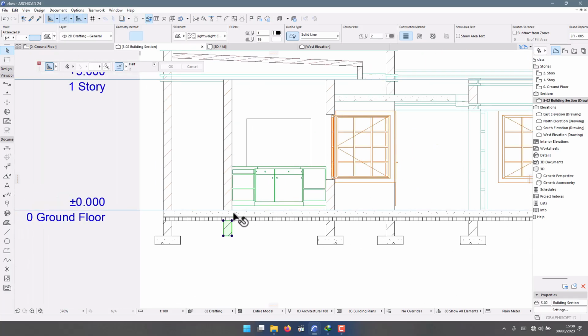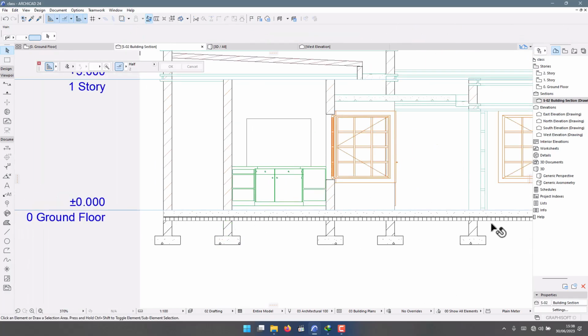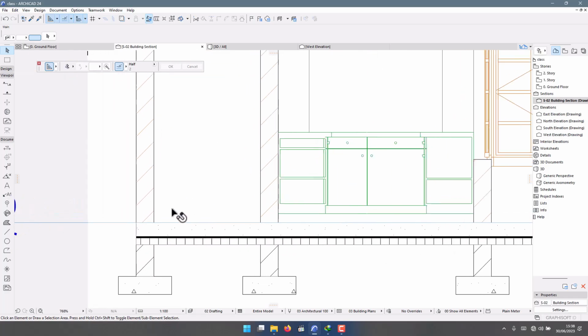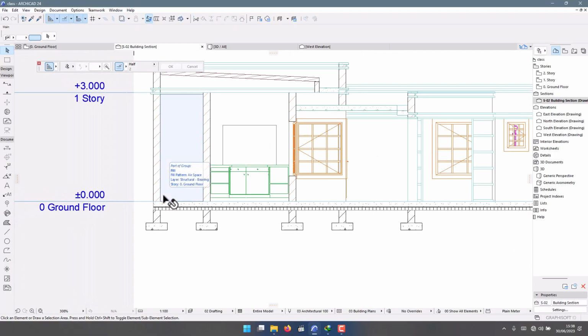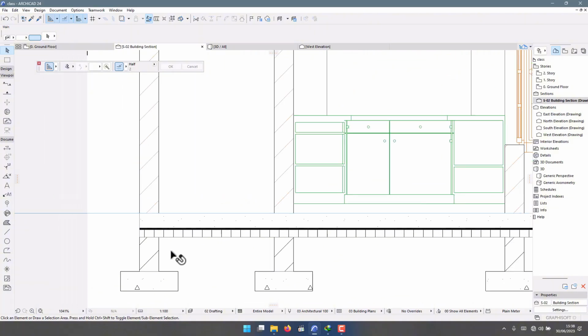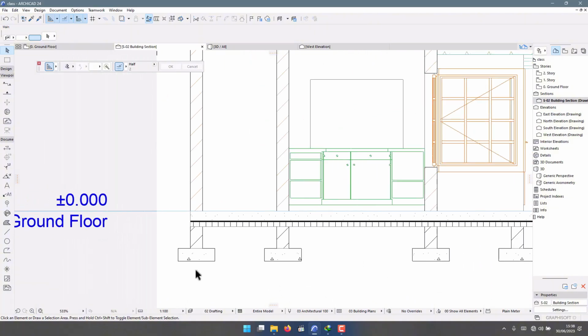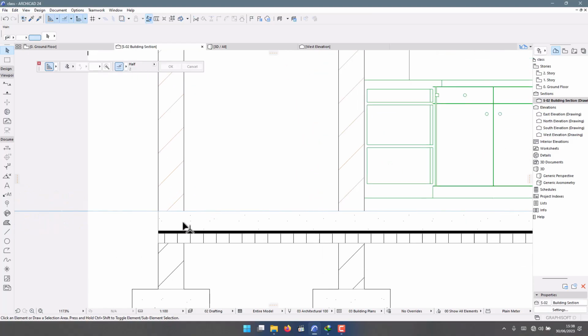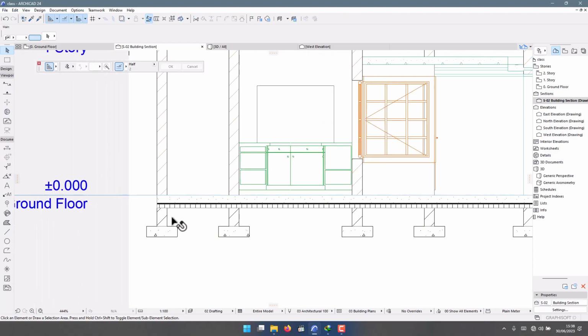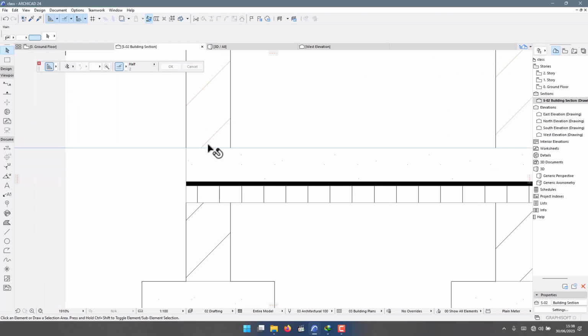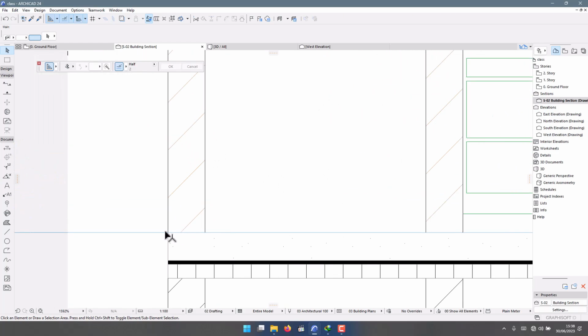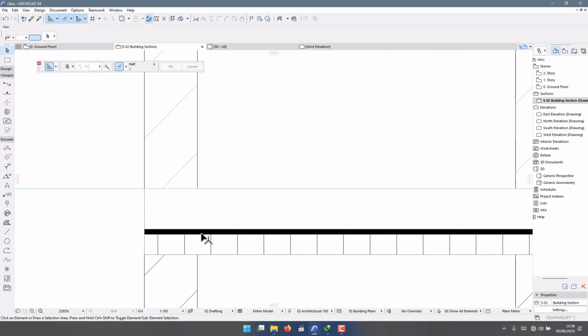And for me, I personally prefer that you build this, then you pour the slab first before the wall goes upwards. That way, if you have water issues, the moisture that penetrates through the wall, if you have a continuous wall from the bottom, you are likely to have that issue. But when you have it this way, you usually have one here, then you come here, you have again a damp proof course here, and this is the damp proof membrane.